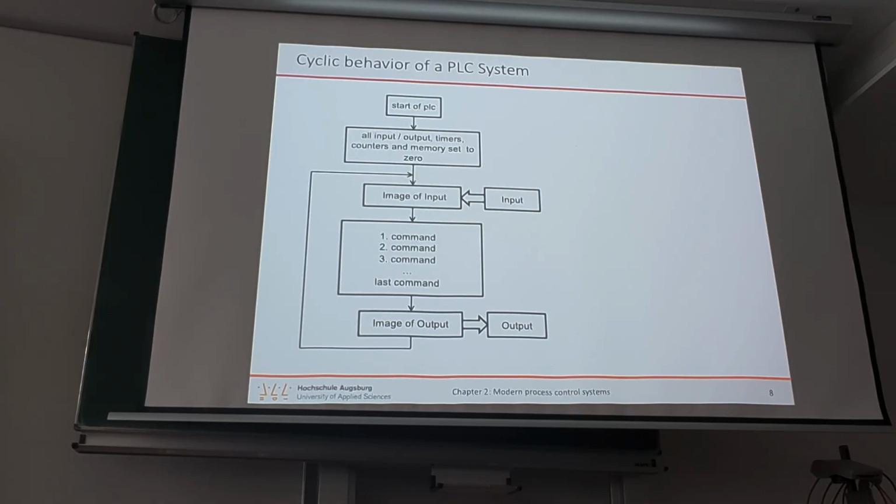time. And we have the Siemens system, and the Siemens system, if you want to have that installed on your machine, you can come to my lab, and we have keys to work with the TIA Portal for 1 year for students. So basically all of the functions of the TIA Portal are then available, and you can program a virtual PLC controller. And I also have a simulation, there's a very small simulation in the PLC controller already. There you can see the I/O and you can manipulate them by hand.